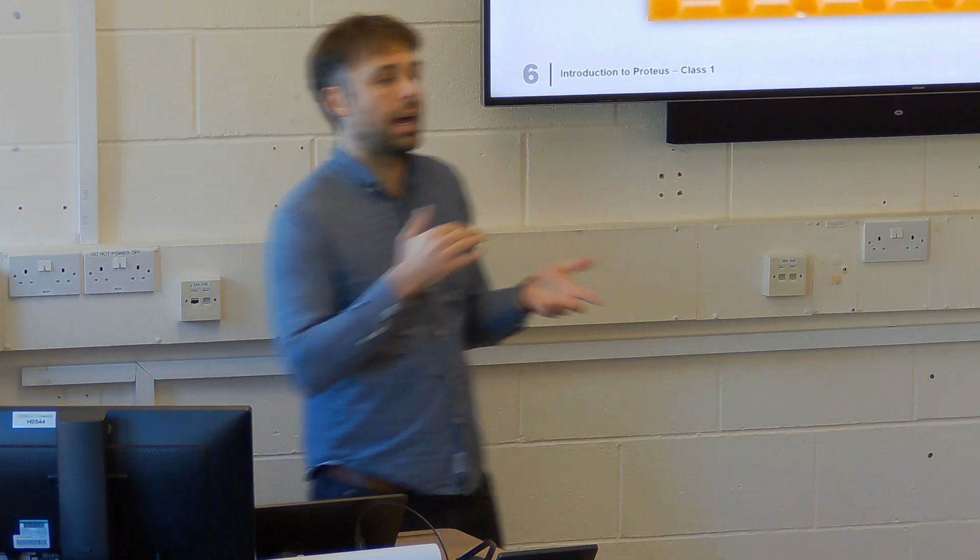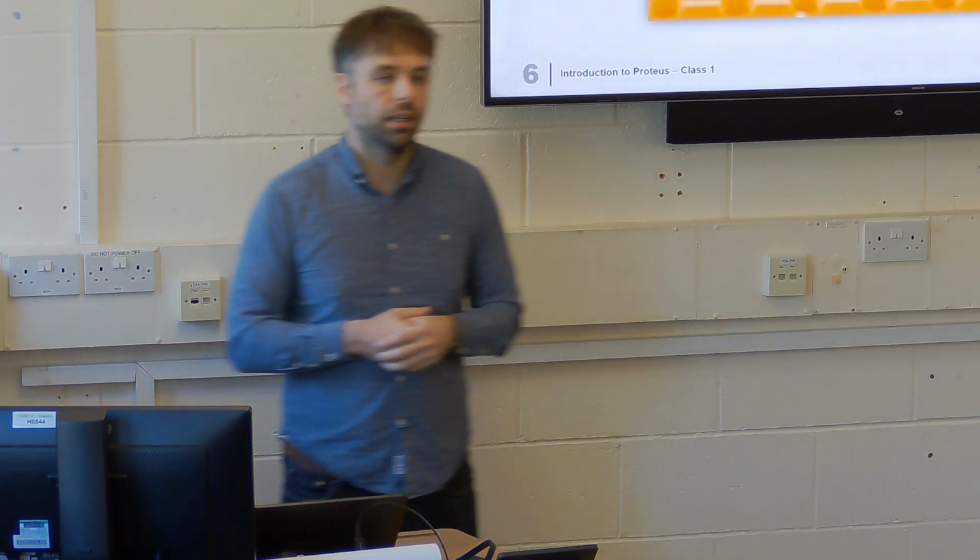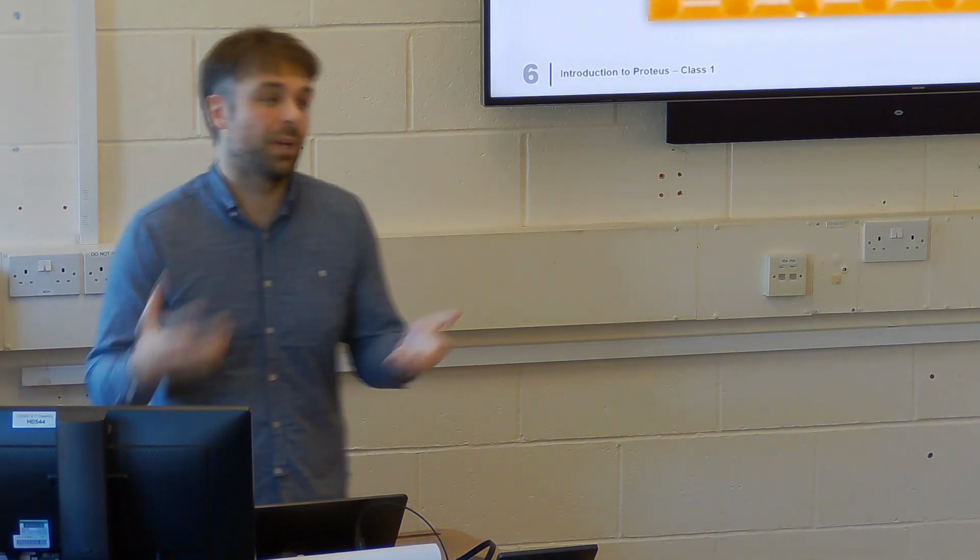Yeah? What's a cold joint? A cold joint is when you haven't heated the solder up enough for it to flow over the two pieces of metal that you're trying to join together. So it's essentially a higher resistance solder joint. You're not expecting it.